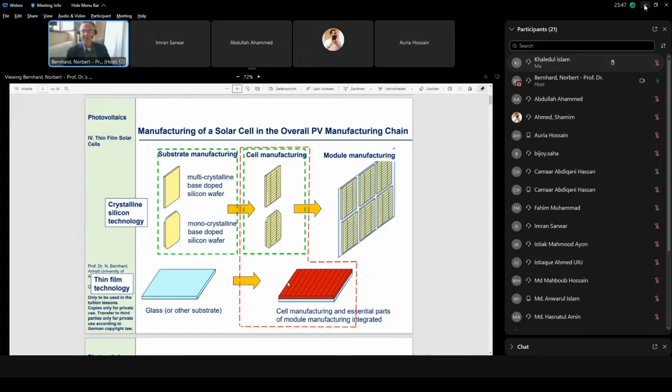In this way we can not only deposit amorphous hydrogenated silicon, we could also deposit microcrystalline silicon, I will explain later what it is, just by varying the hydrogen content in this first chemical reaction. And as I also mentioned last week, this material is also important for the so-called HIT or heterojunction cell. This was a topic of last week.